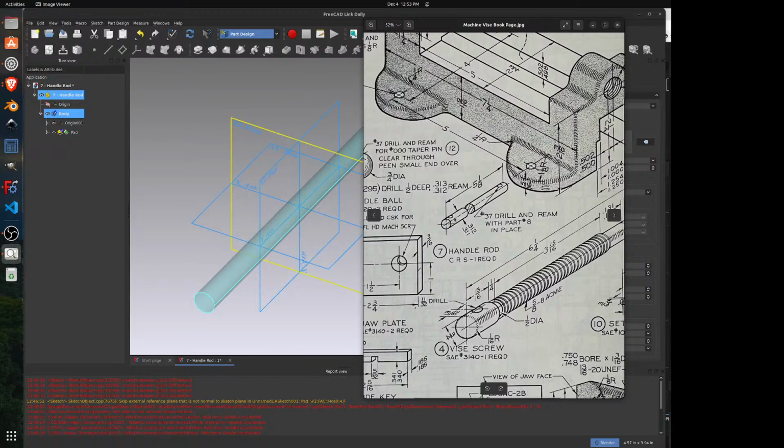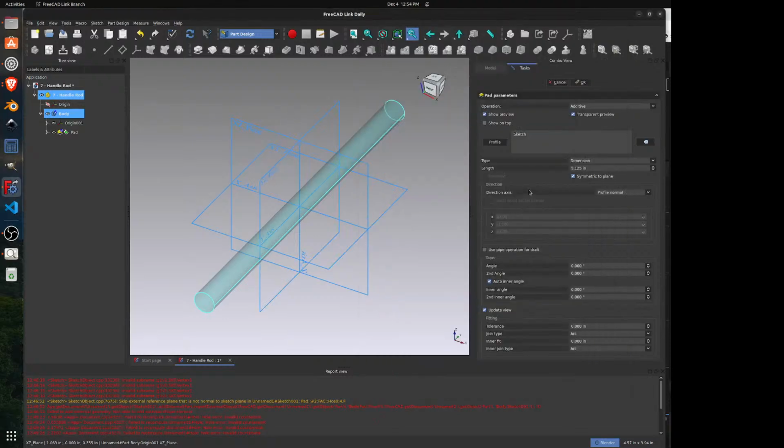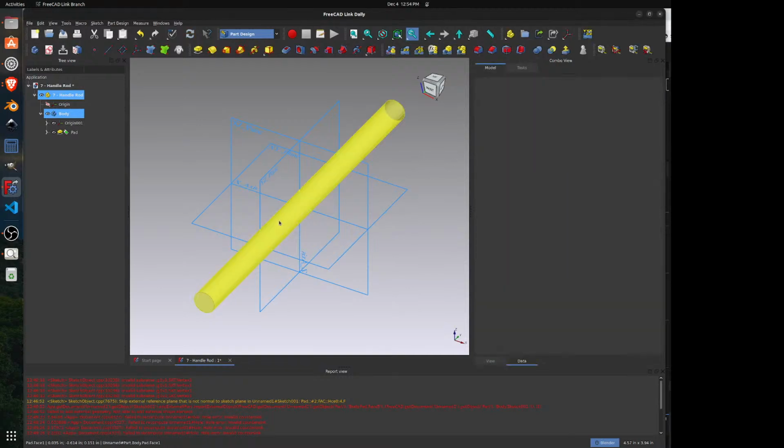And I can make those holes symmetric about a horizontal center line, and I can simply define the dimension from one end if I want, and then the other end can follow. And it just takes minimal dimensions and constraints. But anyway, let's see. So yeah, we got the length, we have the diameter. So there we have our pad.